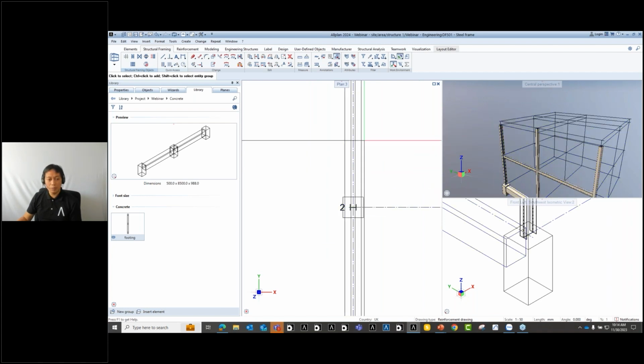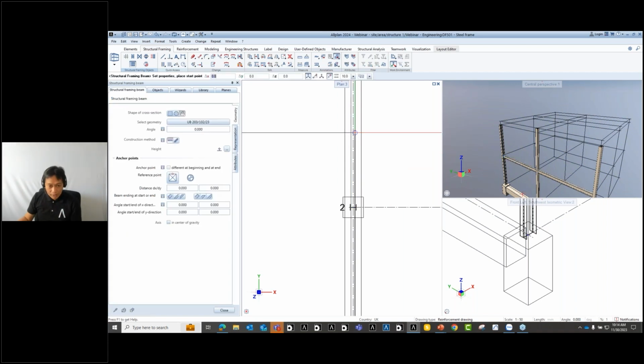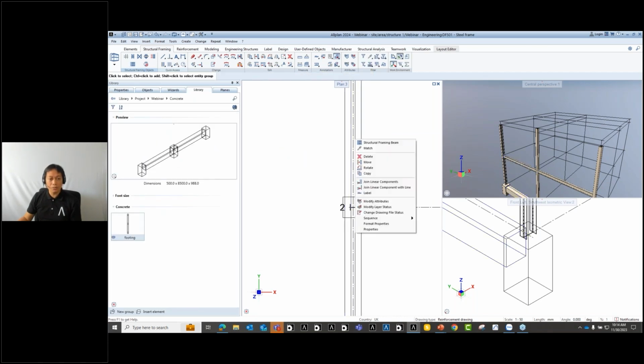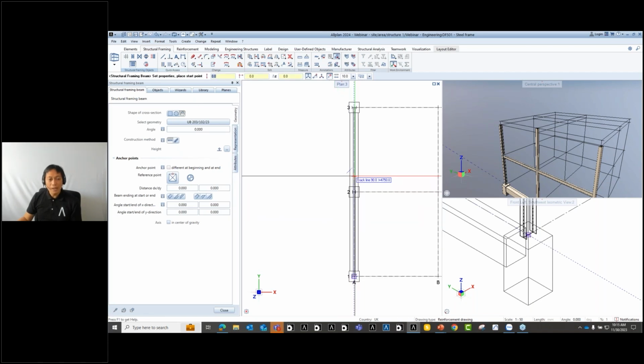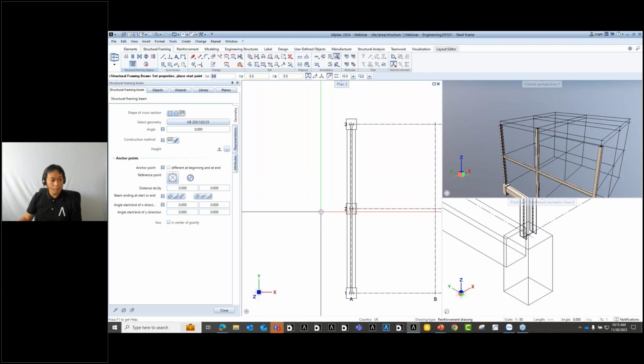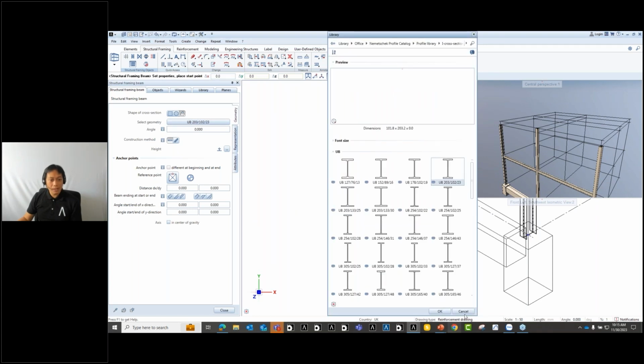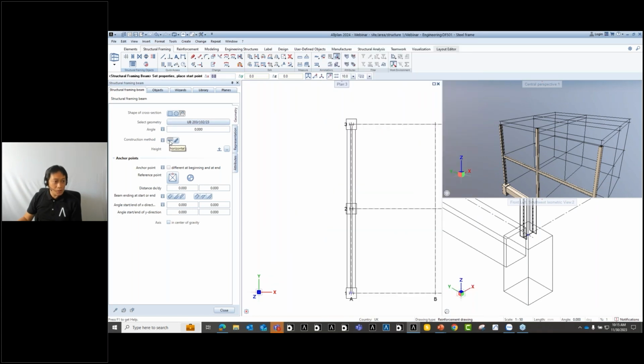So what's next? Basically I want to provide some sloping beam here. Okay, we can use the same. You can just double right click on this, so it will give you the same feature, or you can just right click and then say match, and it will open the same thing. From there, we can say that instead of using the straight or horizontal, I will have to use the inclined. When I say inclined, as you can see here, I have two options already.